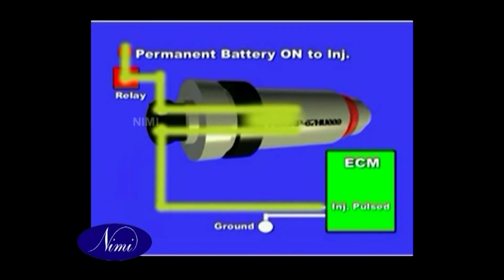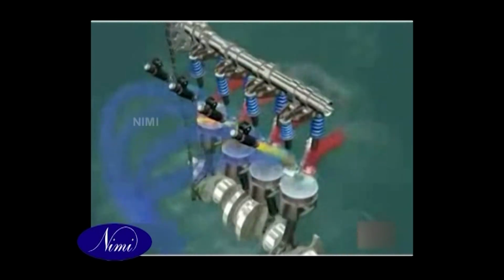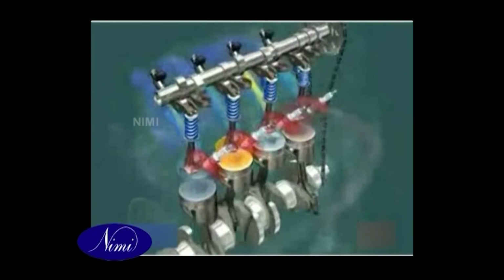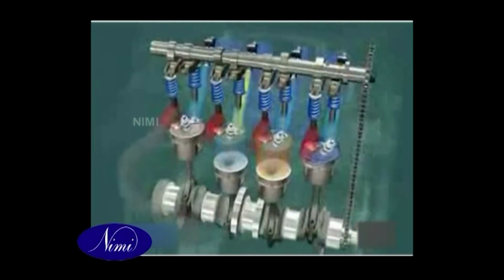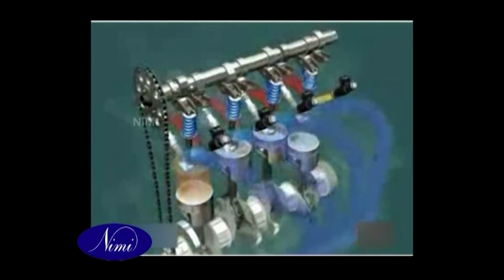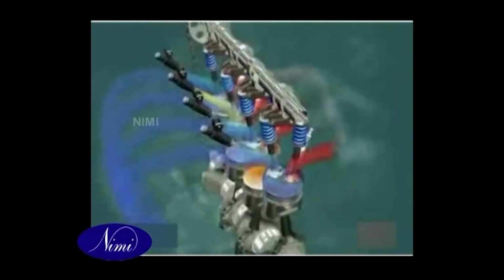Modern systems are all electronic and use an electronic engine control unit (ECU) for metering. SPFI and MPFI. Multi-point fuel injection injects fuel into the intake port just upstream of the cylinder intake valve, rather than at a central point within an intake manifold, referred to as SPFI or single-point fuel injection.